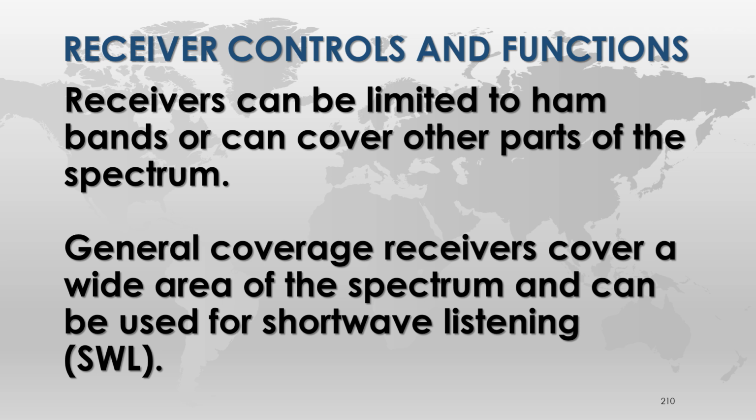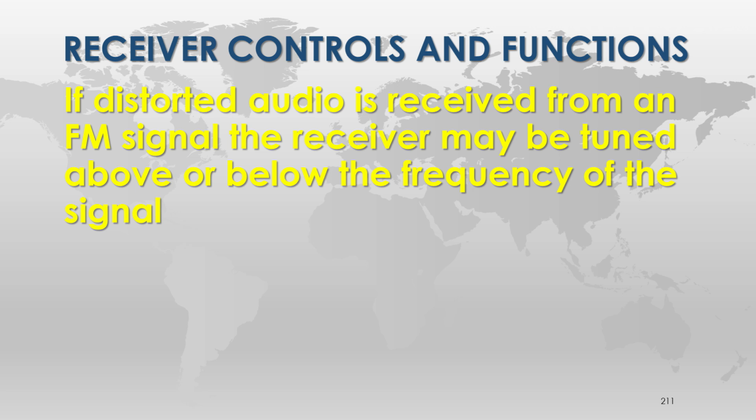The frequency-specific tones available from CHU in Canada and WWV in the US are transmitted on frequencies that are not part of the ham bands, and they are the best way there is to check the frequency stability of your radio. The other thing is, if it all goes to heck in a handbasket, anybody transmitting anywhere in there, you can hear them at least. You can go to an AM station, you can pick it up. Doesn't mean you can transmit on them, it's receiving them.